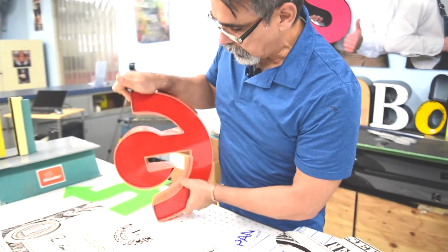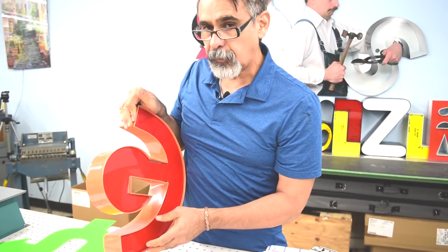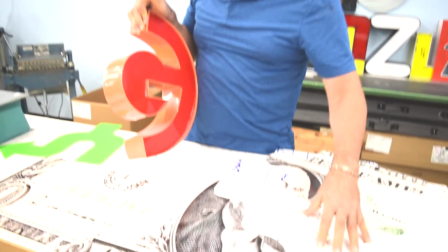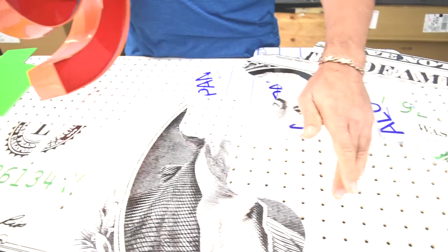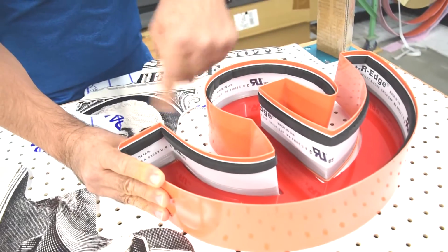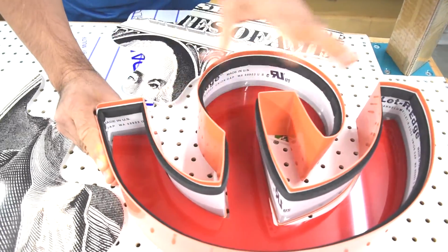Of course, for this letter there are still some steps we need to do. We have to go on to a pegboard table or a magnet table, a metal table with magnets, where you can jig this piece facing down, so you can then apply Weld-On number 4 and then Weld-On number 16 to make this glue joint.